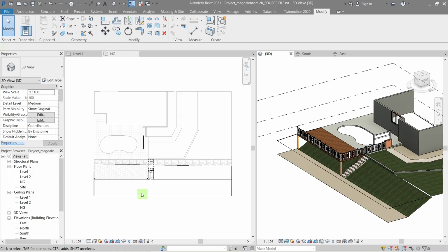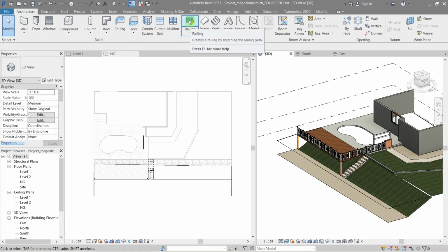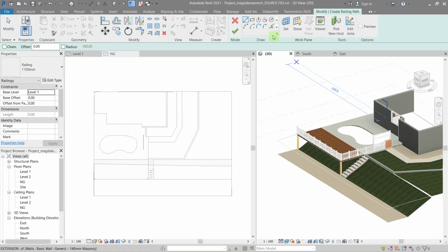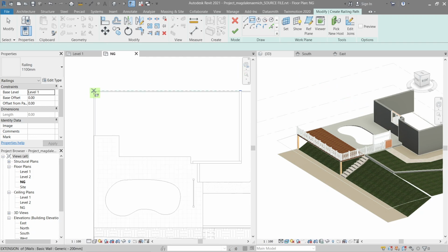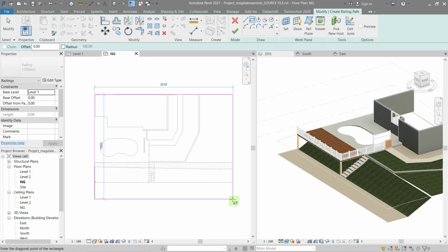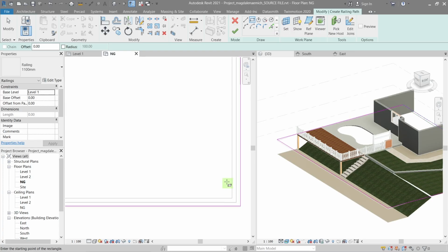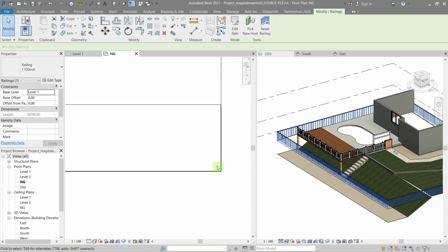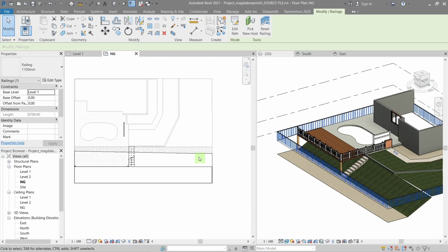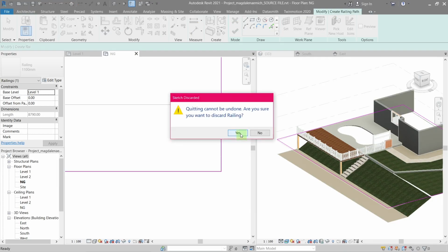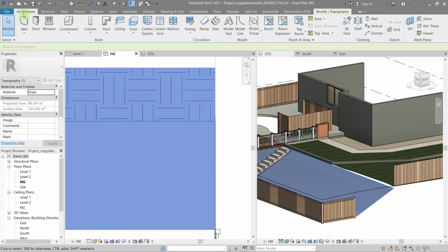And finally, the fence of the house. The fence in Revit is actually a rail with a different family. Download a fence family and switch your railing to the fence in the Properties panel dropdown. One challenging thing about fences is adding one to a sloped surface, which is what we have here. But this is not difficult at all.